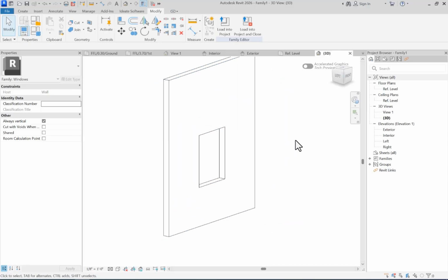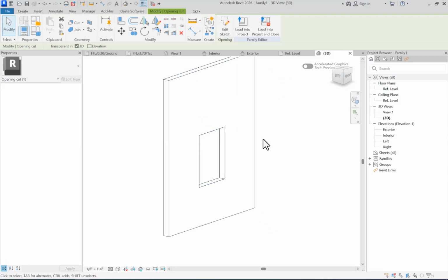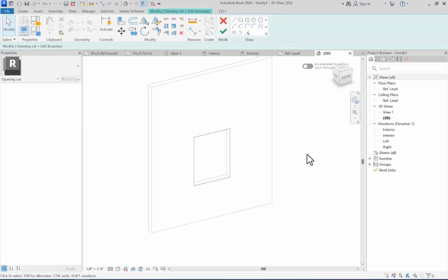And then within that wall, within that base, you would actually see an opening as well. And obviously this opening would be the place in which the window is going to be set. Now, the point to which we need to pay attention is the fact that this opening would only give us a simple rectangular form. So, as a result, guys, to create a more complex window, I mean a window with a more specific form rather than just a simple rectangular form, we simply shouldn't use this opening anymore.